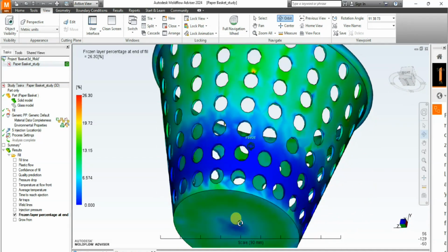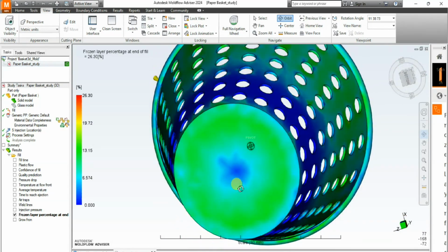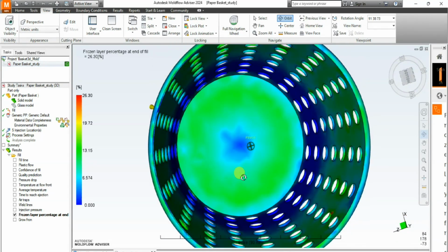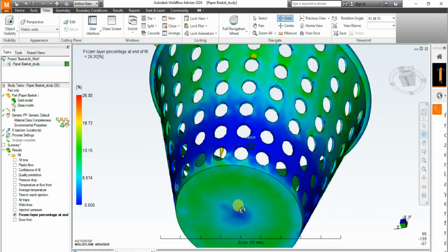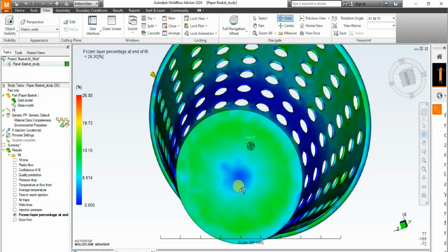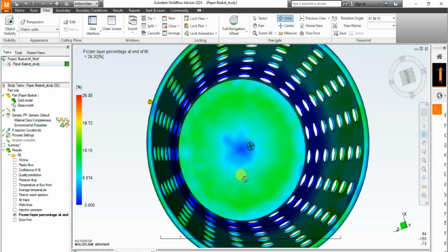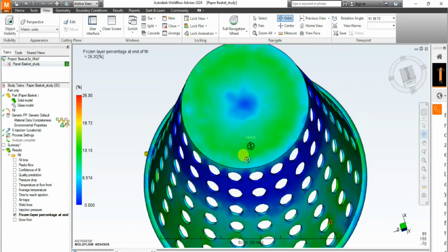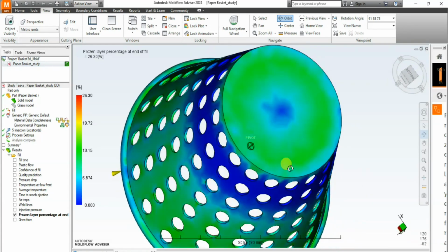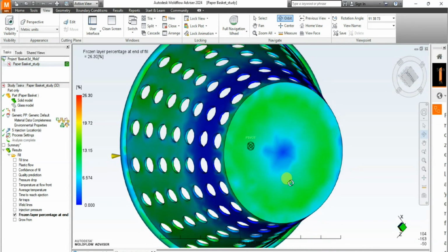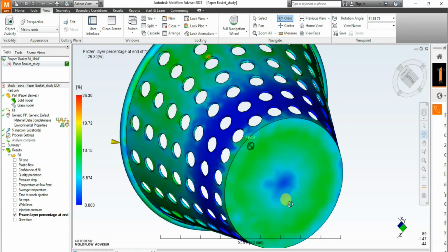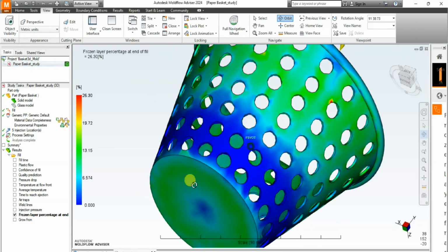Furthermore, frozen layer fraction has very significant effects on flow resistance. The viscosity exponentially increases with decreasing temperature. The thickness of the flow layer is also reduced as the thickness of the frozen layer increases. The effect of thickness reduction can be roughly estimated with the definition of fluidity with representative shear rate. The fluidity is proportional to the cubic power of the part thickness, a direct proportionality.